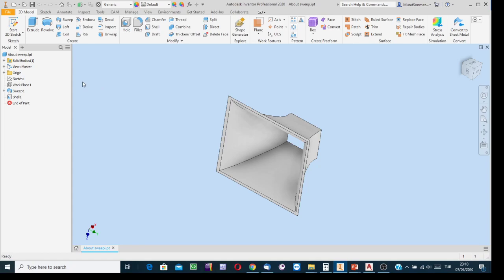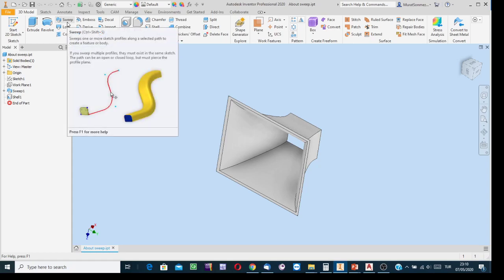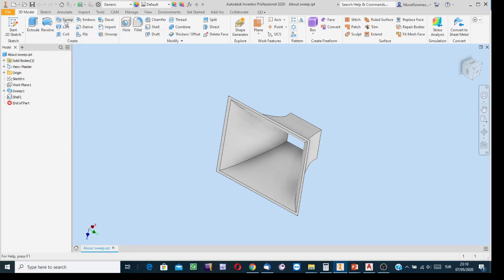If the prism is not a right prism with the same cross section in shape and size, then apply not the extrusion process. But if the cross section is constant in size and also in shape, but the prism is not straight, then you can create the model of it using the sweep facility.